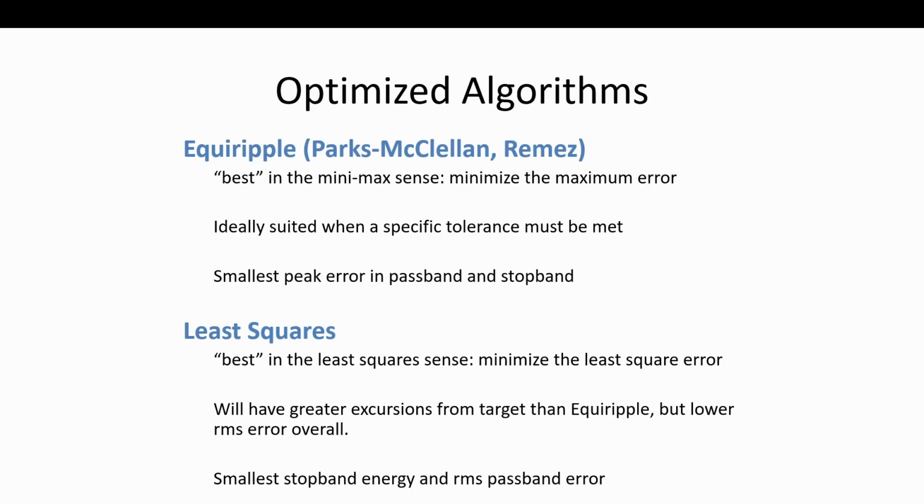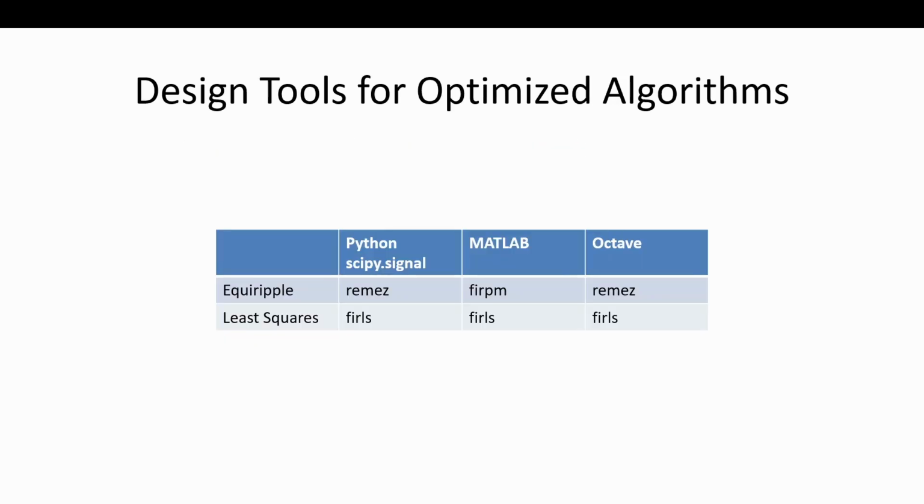So if you're looking at EVM of a waveform, of a QAM waveform or something like that that's filtered with this, your EVM will be much lower than if it was filtered with Parks-McClellan, where that passband ripple degrades EVM, for example, for wireless comm folks that got exposed to that. Any questions about that top view?